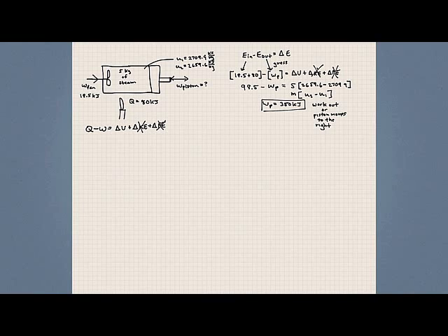And if we look at our sign convention, we can say that 80 kilojoules of heat added to our system, when we add heat transfer or heat to our system, we'll assume that is positive. So I'll write this as 80. When we have work done on our system, we'll assume that that work is negative.